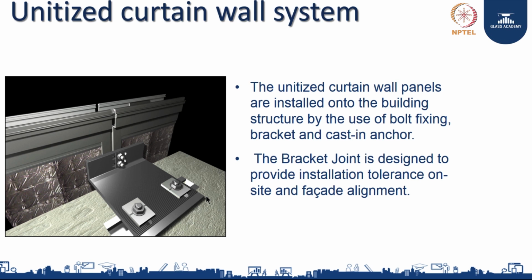This is the only one you do on that side. So this is your casting channel, this is your bracket. You do all your setting out, in and out, where you want the bracket face to be. You have serration here, which allows the locking of horizontal movement, and this bracket design itself will take care of all sorts of tolerances required at site to get a good system fix. And then what happens here, it transfers the dead load. So the bracket design takes care of dead load first. Second, it takes care of restraint against the wind as well.